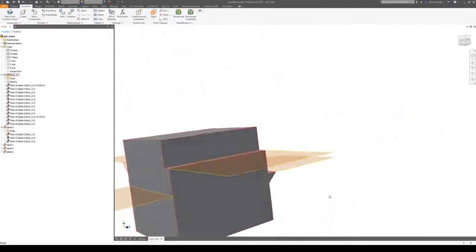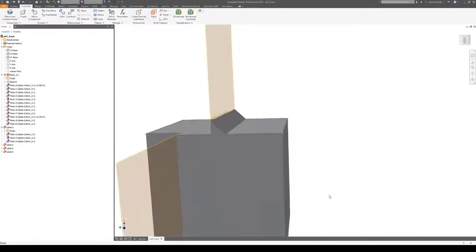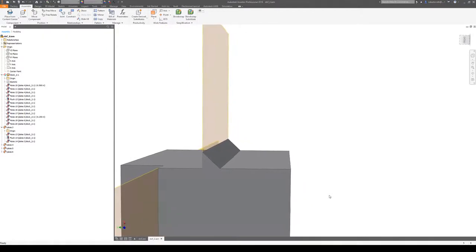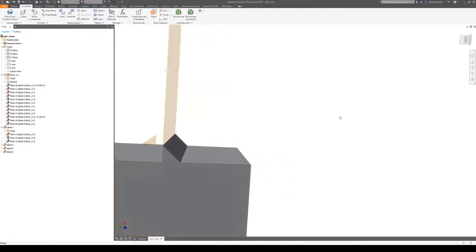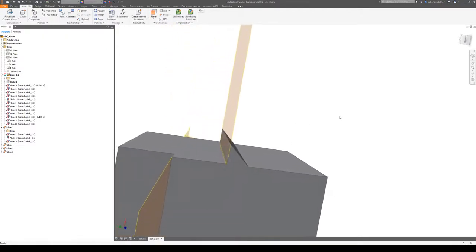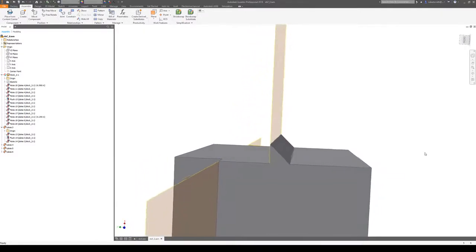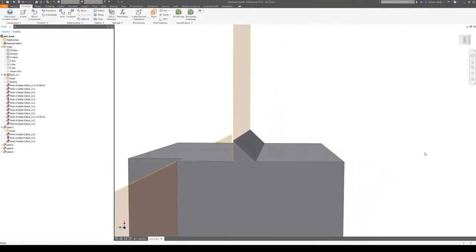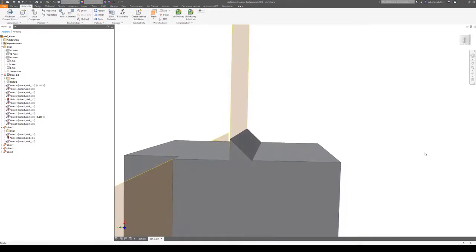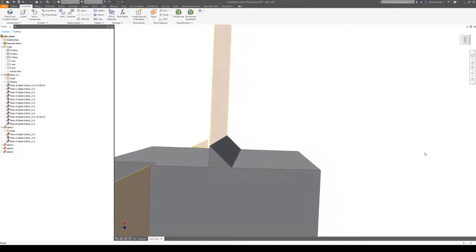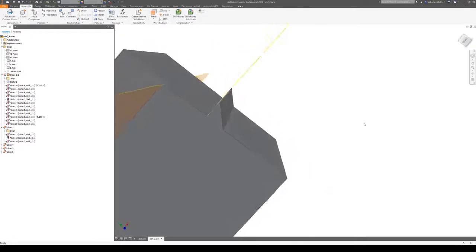I've seen cases like this where maybe it was a weldment where the plate structure and the solid were going to be joined together with a weld bead. We do frequently discourage trying to model weld beads in FEA simply because you're oversimplifying what is a very complex problem.